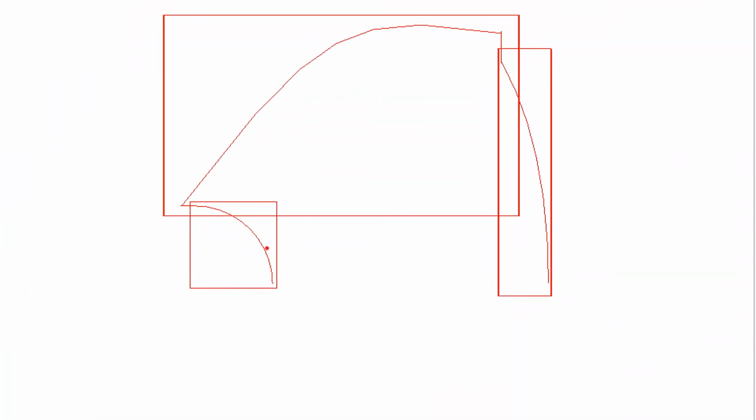So this curve is the first segment that follows the profile of the light emitting diode. There's then a small flat, which is curve 2. Curve 3 is this larger sweeping curve that defines the edge. We're going to optimize the shape of this curve. Curve 4 is a flat piece that joins to the next curved surface. And so curve 5 is the final curved element here. And curve 5 we're going to optimize also.